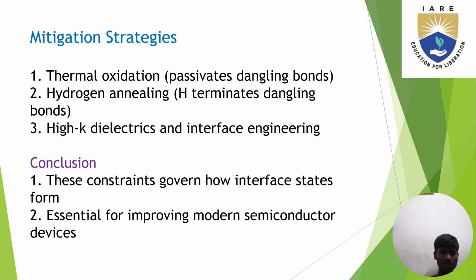Mitigation strategies. Thermal oxidation passivates dangling bonds. Hydrogen annealing, H, terminates dangling bonds. High-k dielectrics and interface engineering.